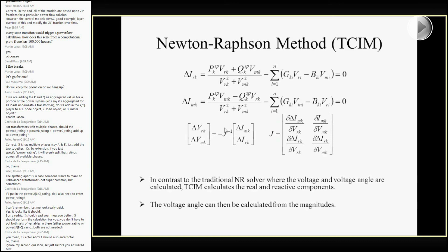I've never actually looked at it, but I would imagine there's a particular system size where both of them are the same, and then if you go to a bigger system, forward-backward sweep might be faster or slower, or Newton-Raphson may be faster or slower. So a lot of times, as I mentioned earlier, your solution method just comes down to topology concerns, or if there's a particular functionality or equipment piece inside GridLAB-D that dictates you use one form or the other.